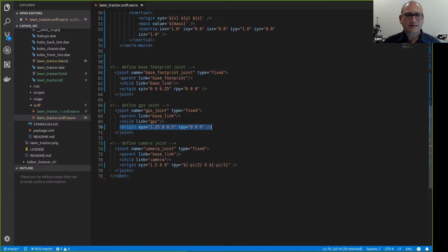Well, forget about the base link. I want to get it into my odom frame. How would I get that into my odom frame? Or maybe how would I get it into my map frame? Or something similar. That's when the link definitions and the references come into the picture. Because if you're getting your GPS data in your GPS reference frame, you can easily calculate it in your base link frame, just because it has a physical dimension.